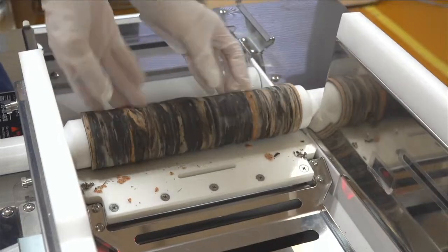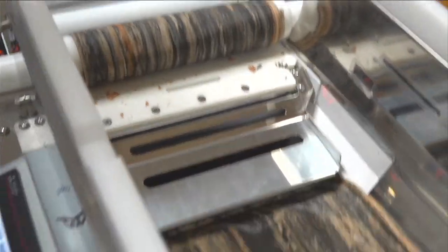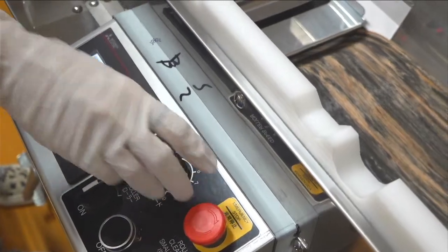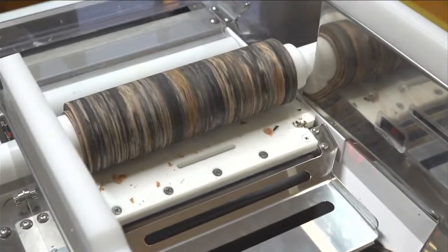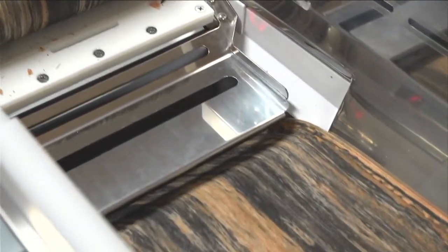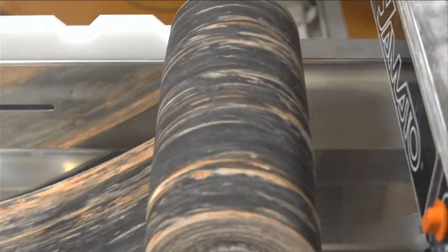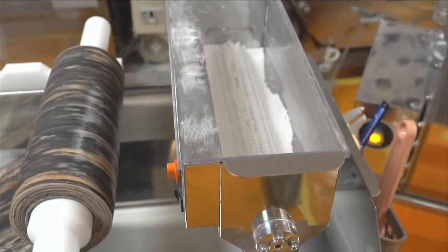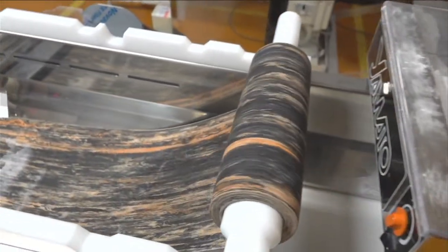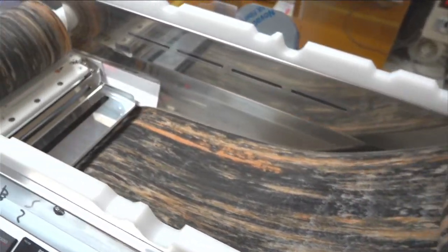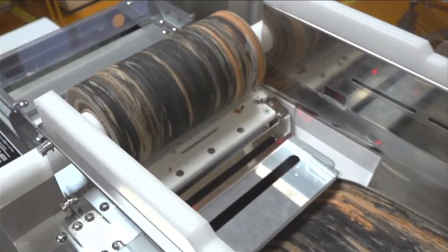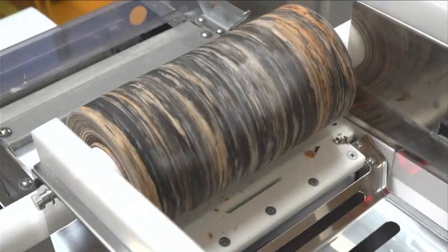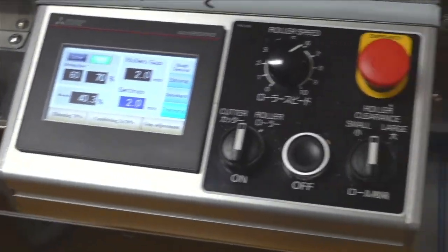So each round of thinning reduces the roller gap by 30%. It was 3 millimeter before, and now it's thinning to 2 millimeter, 30% thinner. From this point on we are going faster than before, because through the combining process the dough is complete in terms of noodle texture, so you can go faster.